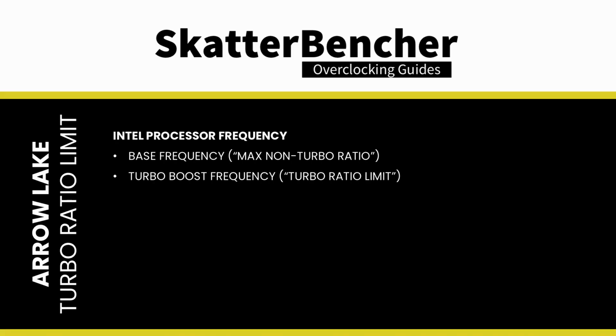Intel processors usually have two types of CPU core frequencies specified: the base frequency and the turbo boost frequency. The base frequency is also known as the maximum non-turbo ratio, whereas the turbo frequency is usually referred to as the turbo ratio limit. Turbo ratio limit is called a limit because it's not really targeting a certain frequency, but it's rather limiting to a certain frequency.